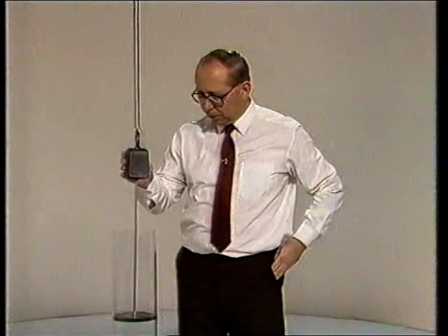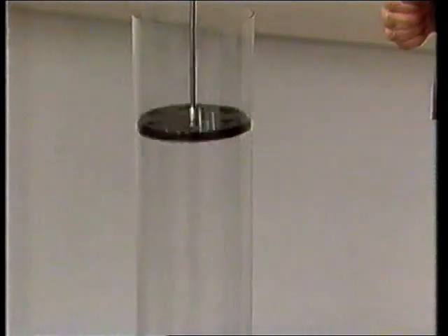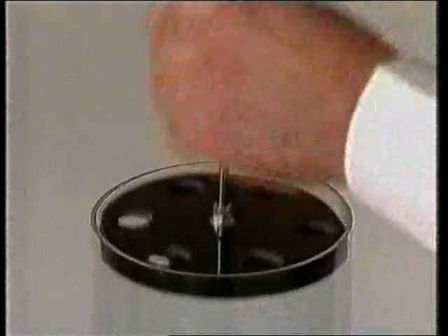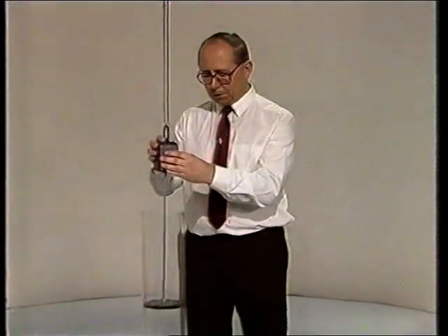And we'll see that the damping force is increased and the amplitude of oscillation dies away quite quickly. In fact, I can increase the damping by making the holes smaller. If you look at the effect, the oscillations die away even faster.